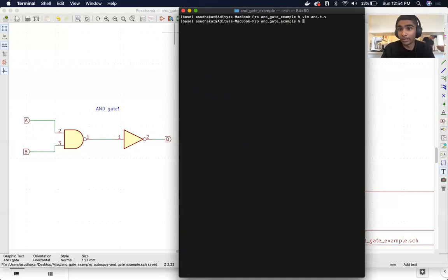Okay, so to compile Verilog code, similar to C, you have your compiler, so iverilog, then you use -o for output. You give your output file a name. We'll just call this nand_test. And you feed in the file you want compiled. So in this case, it is nand_tb.v. We want to feed in the test bench, not the Verilog file, not the modules file.